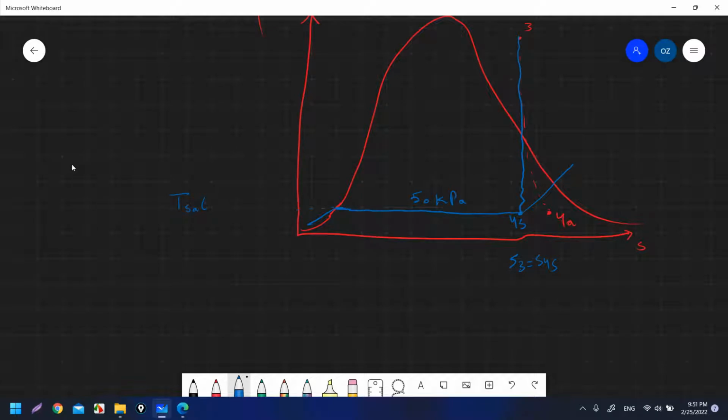When we say subcooling, it means we go down from this saturation temperature by a small value, which is given in the question as 6.3 degrees Celsius. Here is Tsat, and that means we move down. So let's draw state 1 to be here, for example. This one is number 1. So here is T1.